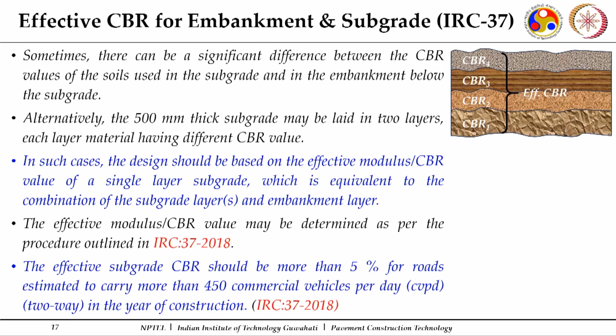Since I am doing my subgrade construction in multiple layers, if I am doing a subgrade construction of say 50 centimeter, I will not be able to do it in one layer, I may be doing it in two to three layers.